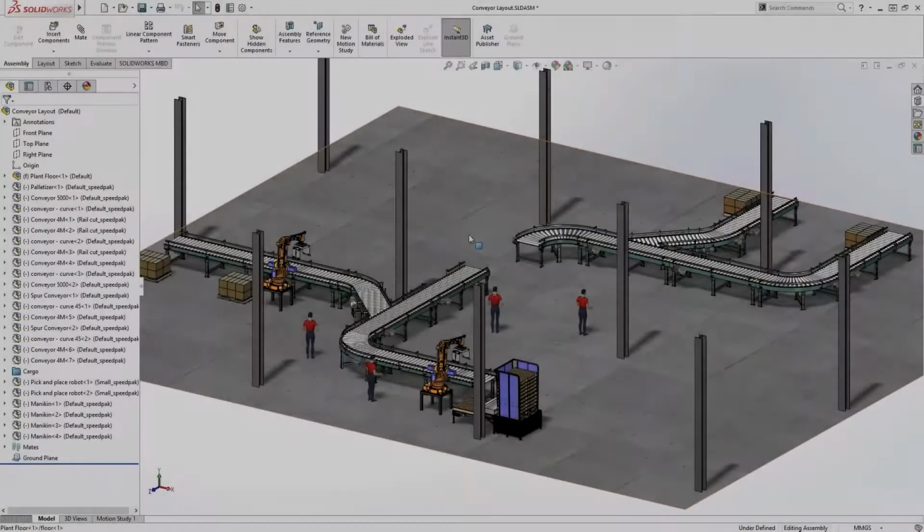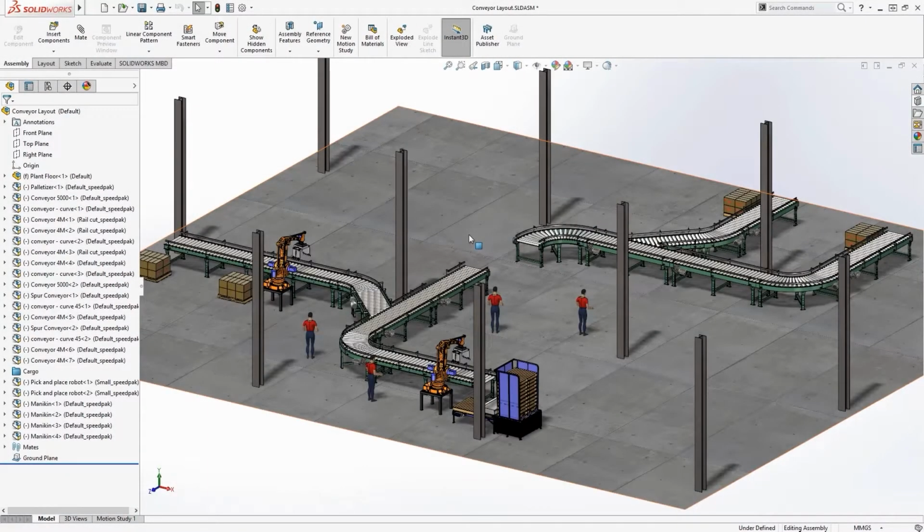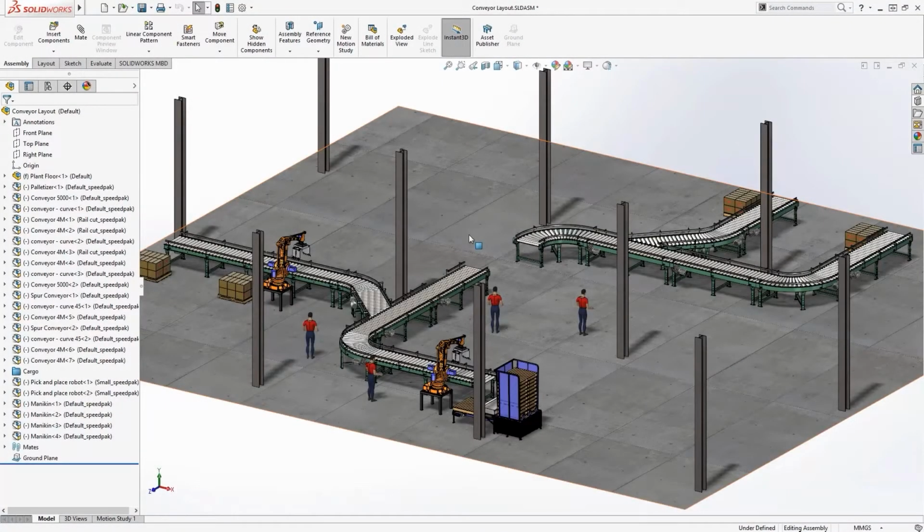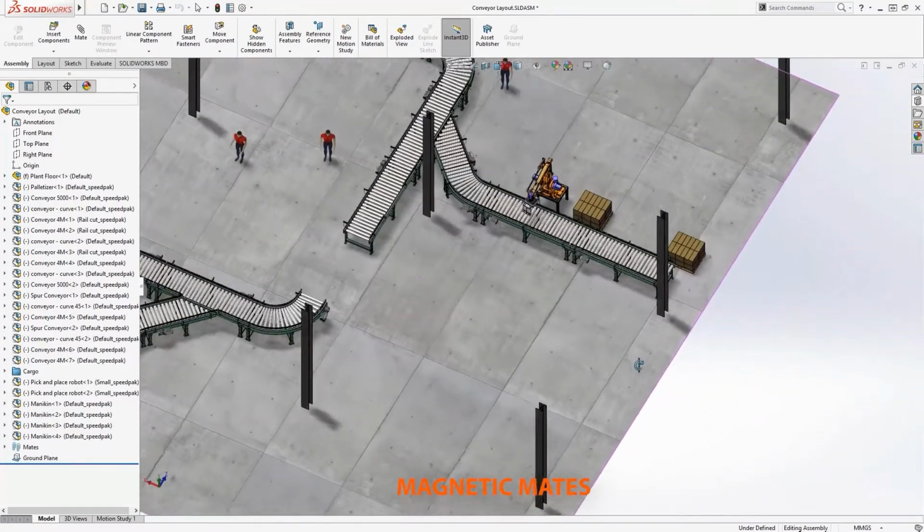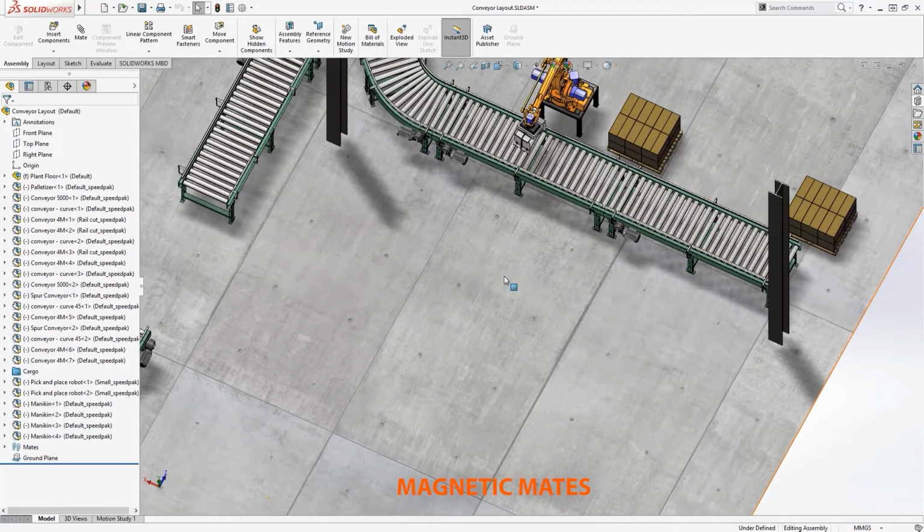Working with large assemblies can often be challenging due to the large number of models that get loaded and the mates needed to represent interactions that need to be solved. This can get pretty difficult when you're working with layouts, maybe to optimize space and organize equipment. I'd like to present an enhanced workflow that directly addresses many of these challenges. Parts and assemblies can be published as assets with appropriate connection points that allow for easy drag and drop mating.